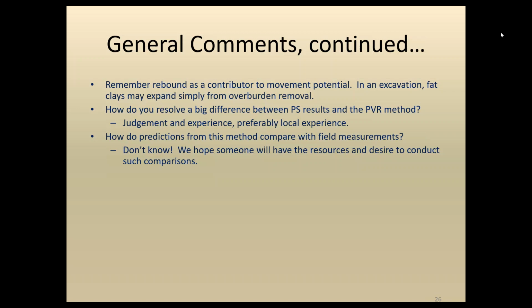And I wanted to just remind folks of the potential for rebound as a contributor to movement potential, and how in an excavation, fat clays that have been excavated may expand simply from overburden removal. And that needs to be considered when estimating movement potential.